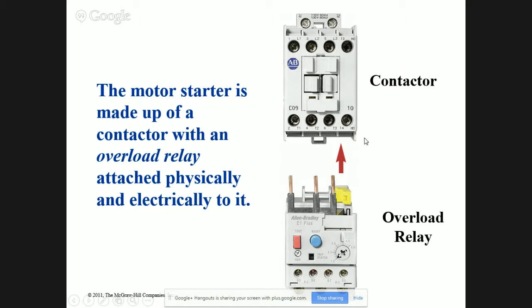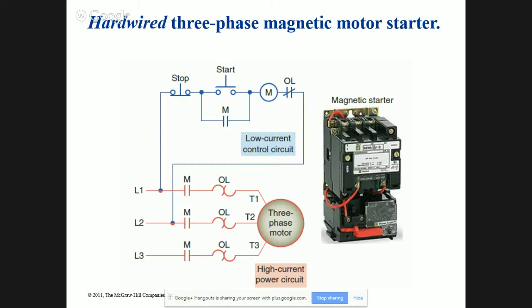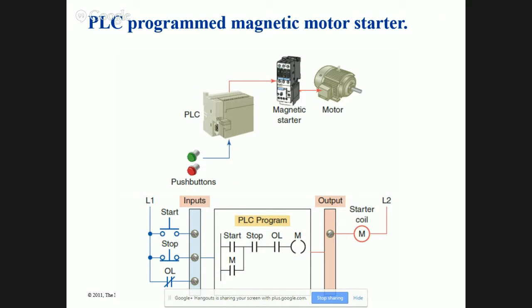Remember, we don't have to have a latching circuit. It's in the PLC. Right. Here we have an old hardwired system. Here we have an equivalent. Notice they put the stop button in front. I don't do that. I always put my stop button in the back. Doesn't matter. It's going to work the same, but that's what I did.